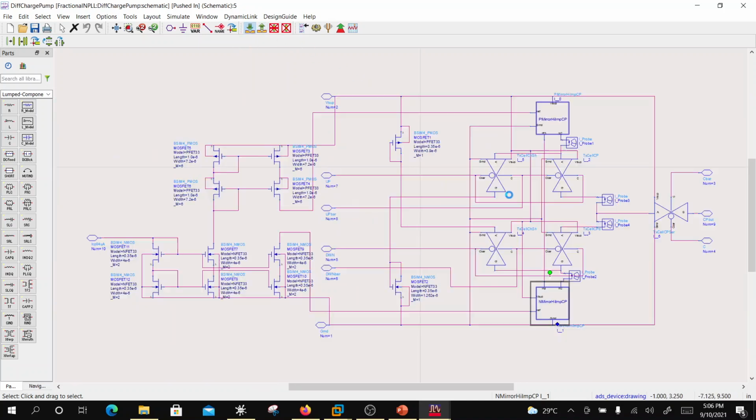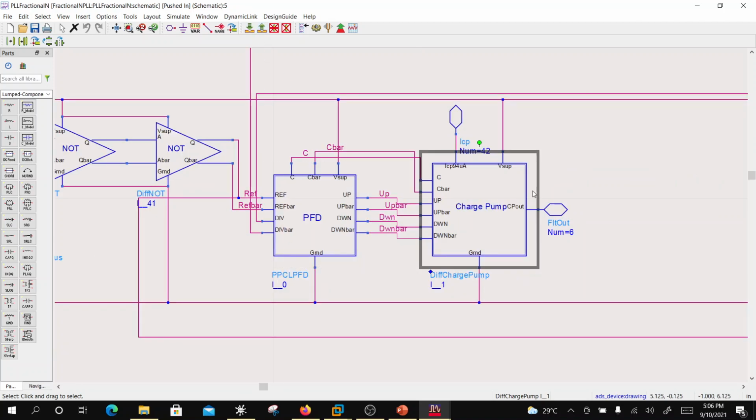And again, there is one more stage here, which is basically a high impedance state. I don't want drooping to occur. Because of leakages in this charge pump, there may be a drooping of the output voltage. So I can cut the output by gating it using a transmission cell. Okay, so this is a current steering charge pump, right?